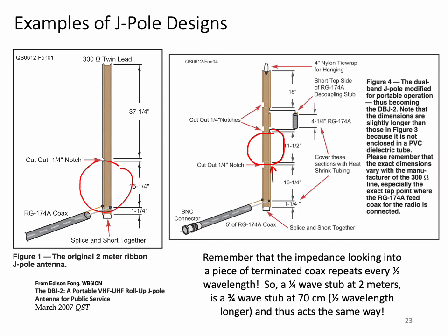But we still need to operate on 2 meters as well. So in order to do that, we can place an extremely high impedance at the top of the 70 centimeter antenna. So if I put a high impedance here, I can essentially choke off, at 70 centimeters that is, what happens in this portion of the antenna for 70 centimeters. But if that high impedance can turn out to be a low impedance at 2 meters, then the rest of the antenna can be used to operate on 2.